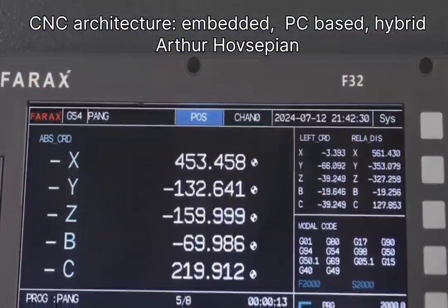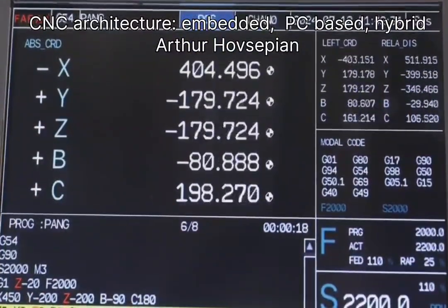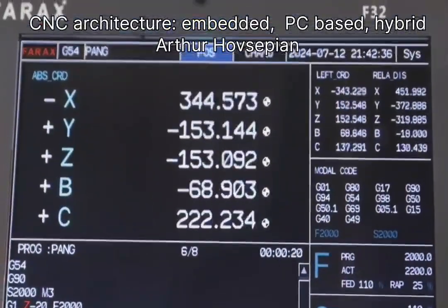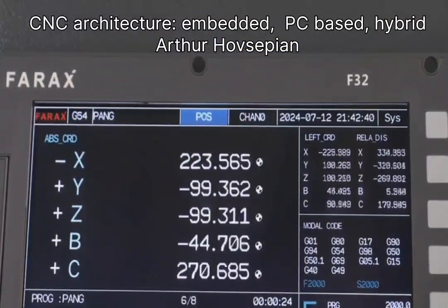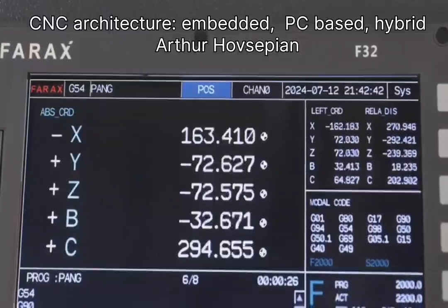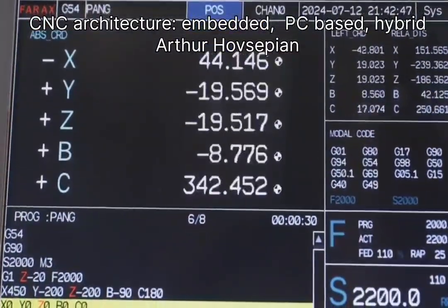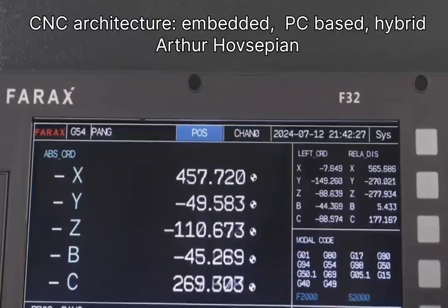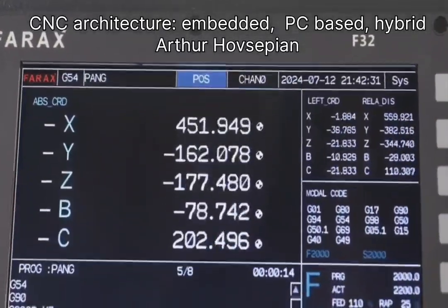Right, embedded. So think of this like all the control tasks are baked directly onto special dedicated hardware. And critically, they use real-time operating systems, or RTOS. RTOS. Okay. Not like the Windows or Linux we use every day. No, exactly. No general purpose OS. Instead, you've got these light, really stable industrial processors. Things like ARM Cortex-R, maybe Intel Atom, or specific microcontrollers.